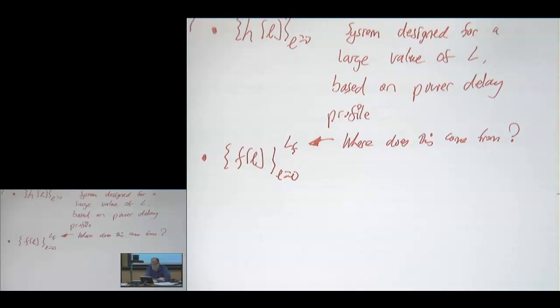So generally, you don't want to pick L sub F to be too long. Also, the longer L sub F is, the more computations you have. So there's some sort of balance in there. Where it actually comes from is an engineering trade-off, and you would probably figure that out through extensive simulations. I don't see a really sexy way to estimate this L sub F.